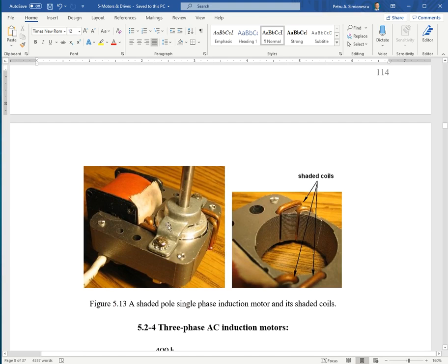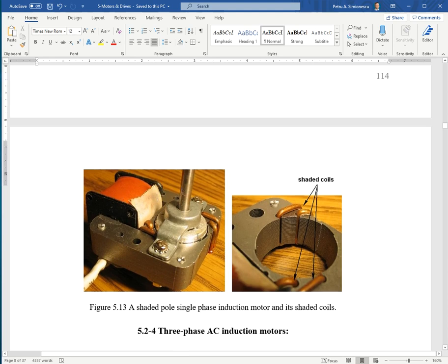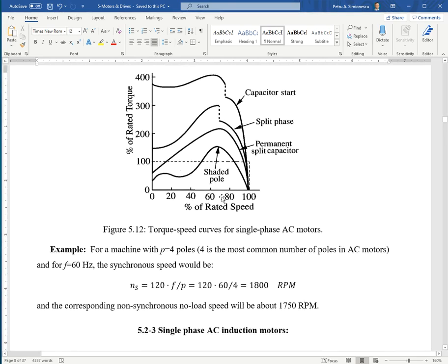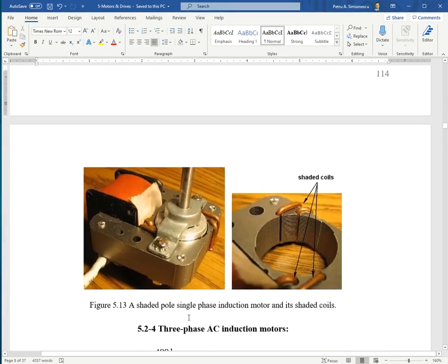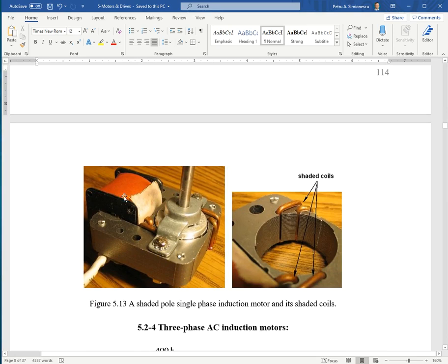You flip the switch, and if you don't flip it back off, the coil gets energized, and not having any circulation to cool it, and the starting current is also higher than the nominal current, you will burn the insulation of the windings and damage the motor.